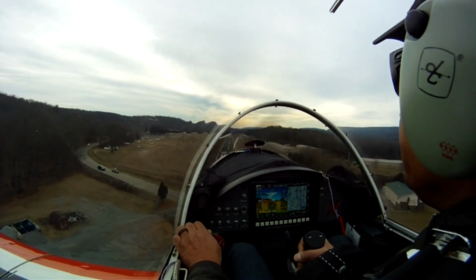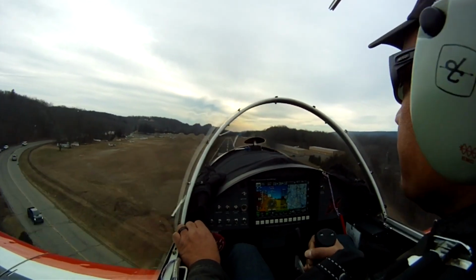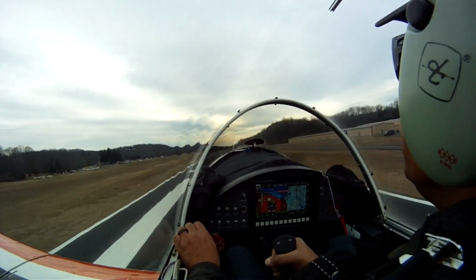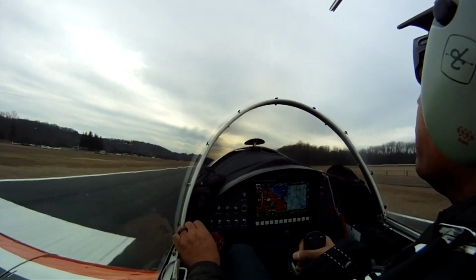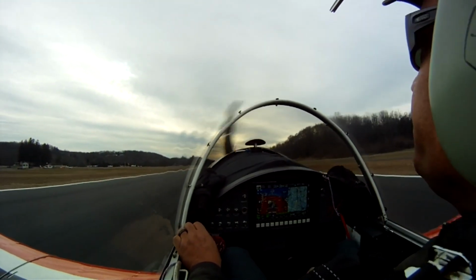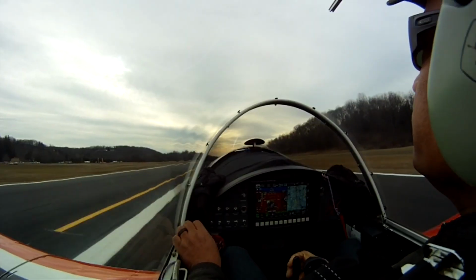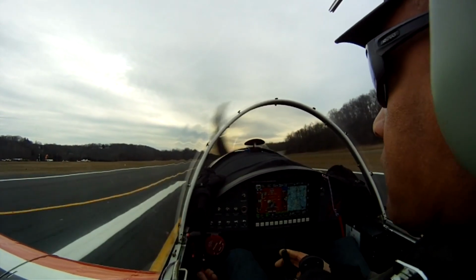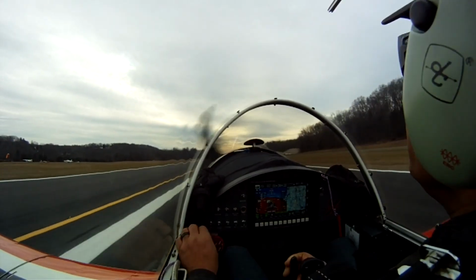After the landing roll, you must come to a full stop on the runway for at least 2 seconds. The stop must be on the landing runway and not on a connecting taxiway. At least one recorded data sample must contain a 0 GPS ground speed value. Additional test flight planning suggestions will be provided at the end of this video.